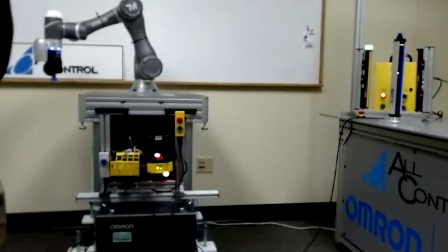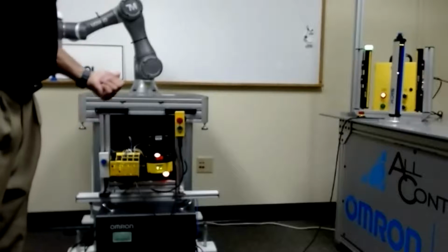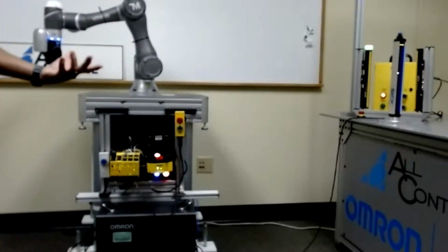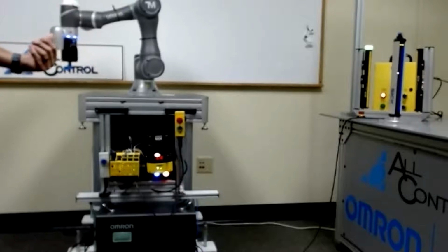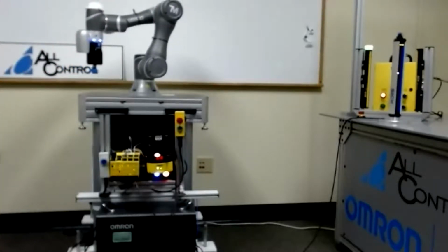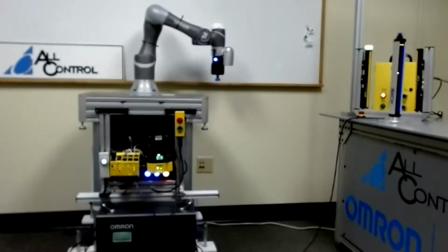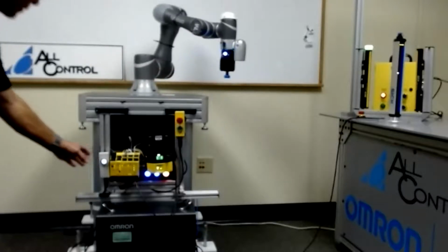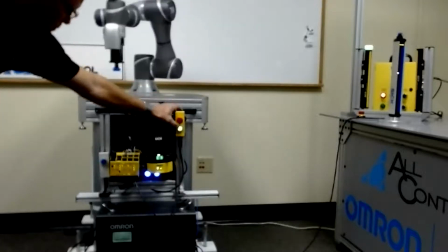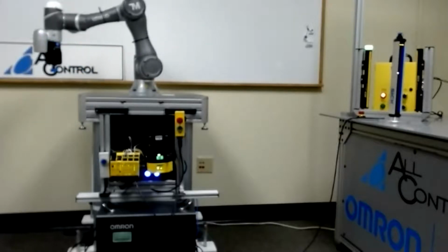So this is your Omron robot. And all we did was tie into the reduced speed, and we tied into the protective pause, but just call it pause. So when I step away from the robot, it should go full speed. I'll show you later why the reset button is on. I want not to have that, but okay.